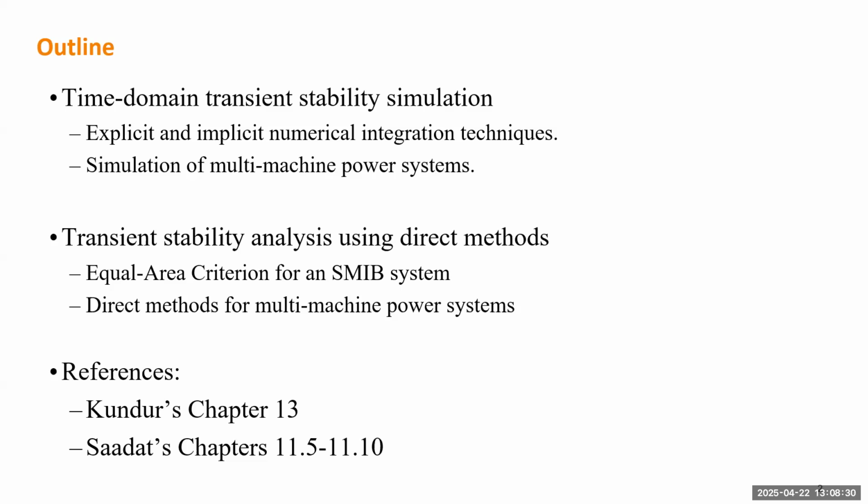Next, we'll also talk about some direct methods. So by using this direct method, you can judge the transient stability based on, for instance, some equilibrium criterion for a single machine infinite bus system, or for using some energy function for multi-machine system.